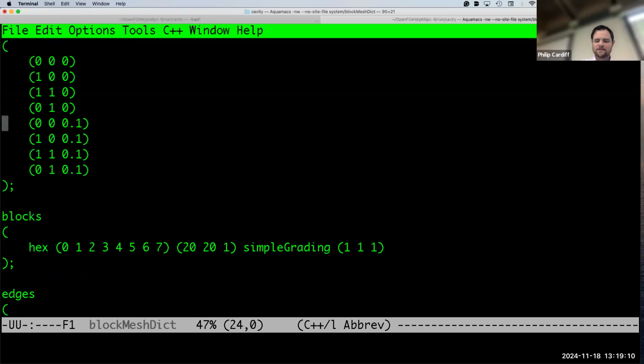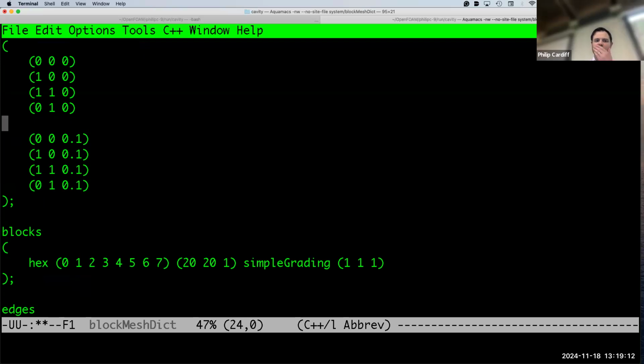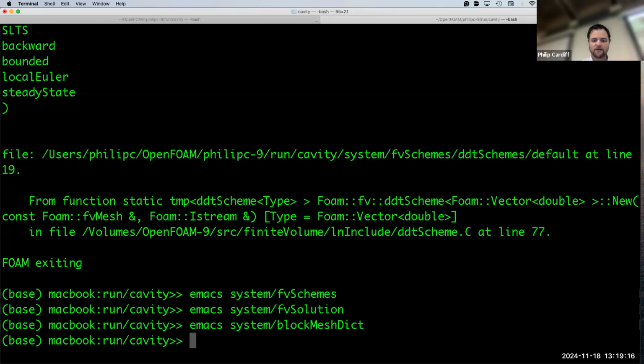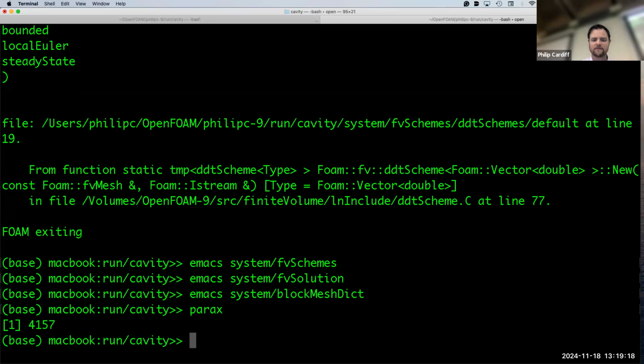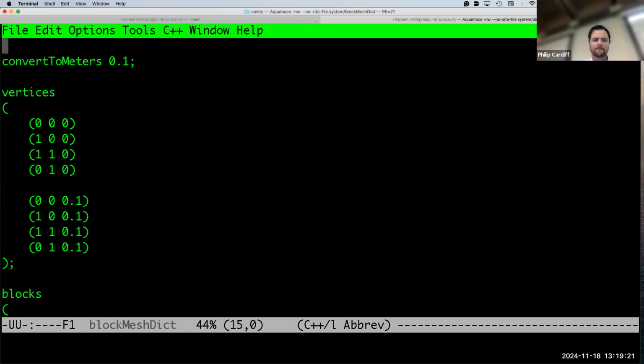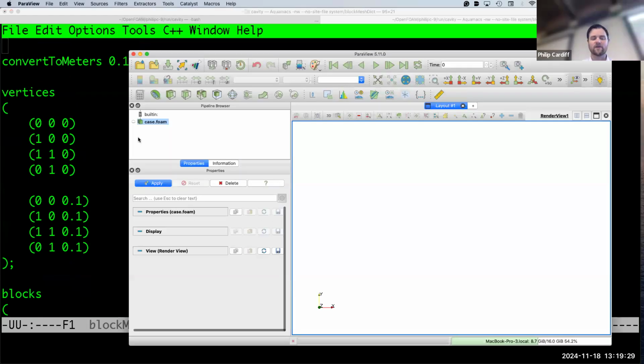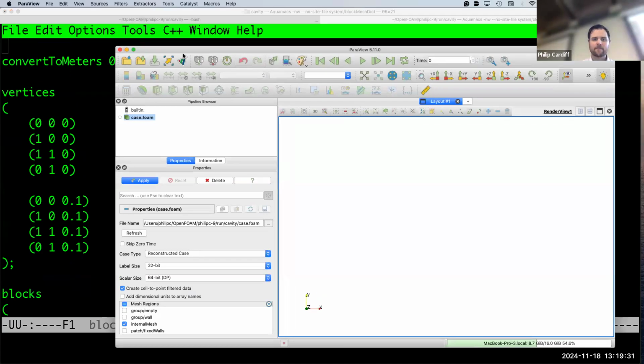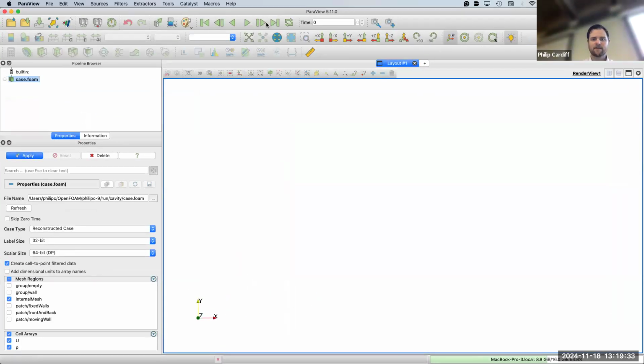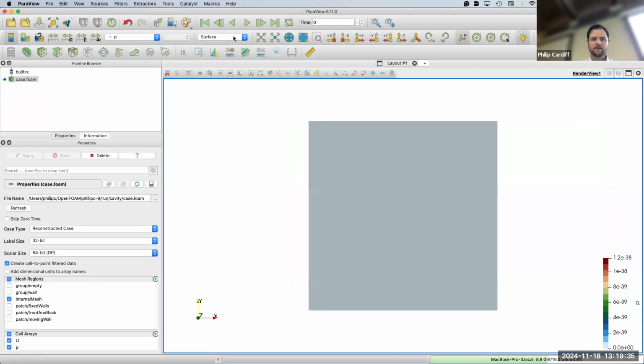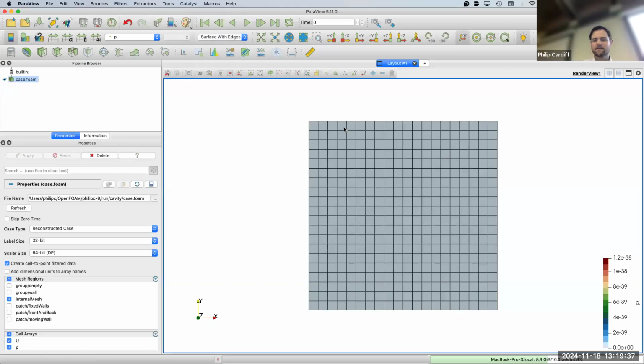Okay, so how does this work? In this case, it's a mesh, and let me just open up the mesh in ParaView so we can have a look at it. It's a very simple geometry. It is just a cube geometry, essentially, or a square. So I press apply, I turn on the mesh. It's a 2D test case. That's just a square.